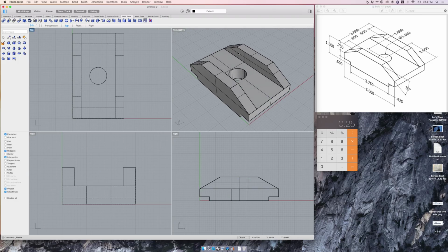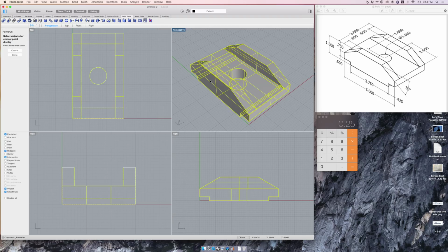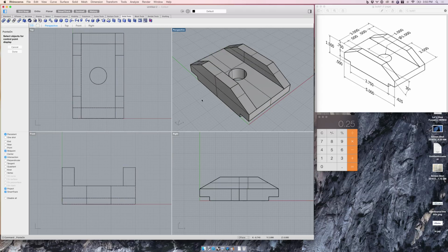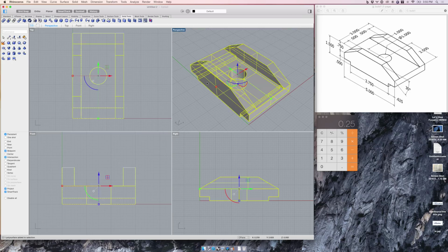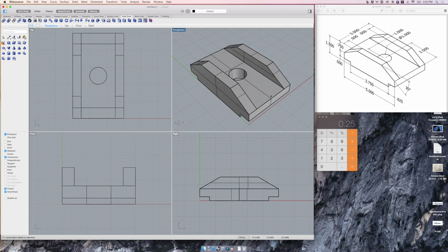And then students always have questions about what these additional lines here are. How were they created? Well, it has to do with control points. So if you hit the function key and hold F10, you can turn on what are called control points. And actually, this surface doesn't create any control points. I lied. It has nothing to do with control points. That's for surfaces. Those lines exist because of the way we constructed the object, and they have to do with individual panels and pieces that can be separated.